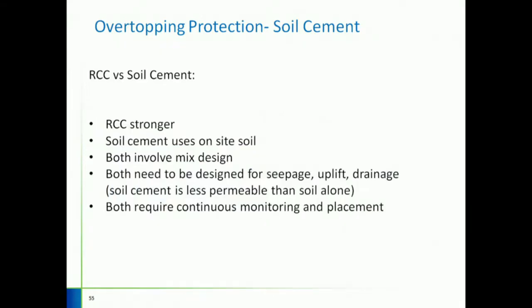So the differences between RCC and soil cement mixtures. RCC is generally stronger, and soil cement uses on-site soil, which is an advantage. Both involve mix design. Both need to be designed for seepage, uplift, and drainage. And I just want to underline that soil cement is less permeable than soil alone. And both require continuous monitoring and placement.